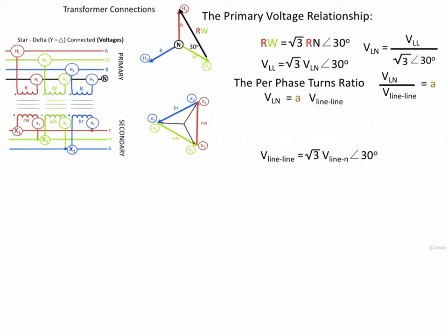This is a phase relationship if there is a three-phase system with a neutral, which we've hypothetically developed. Now I'm rewriting the equation, bringing the voltage line-to-neutral over to the left-hand side. That's all I've just done here, and bringing all the rest of the terms to the right-hand side of the equation, giving us this final equation here.